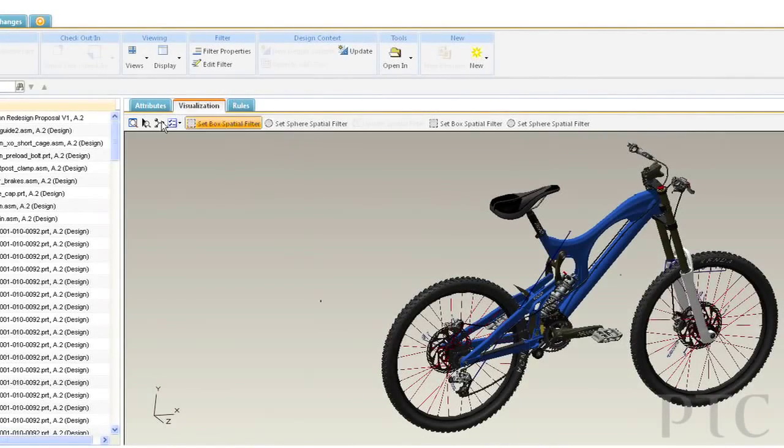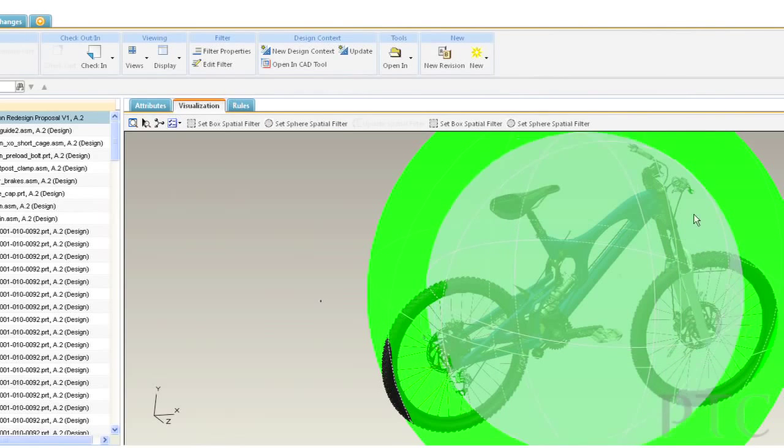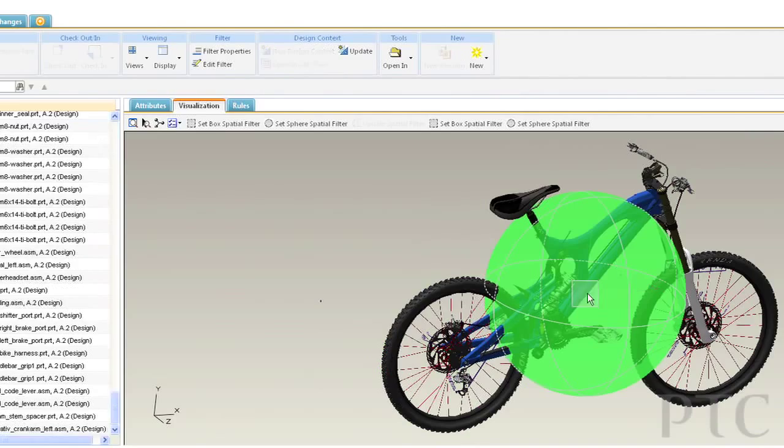The consequence of that is if you want to look at something from a zonal perspective, so I need to work on the underhood compartment, it might turn out that in order to get two things which logically, geographically fit together, you might have to go right to the top level assembly and bring all of that into your CAD session before you can model. Design in context allows you to work inside Windchill, drill down the assembly, filter it out, and then throw a zone around some parts, and then say, just get me that zone into the CAD modeling environment. That's design in context.